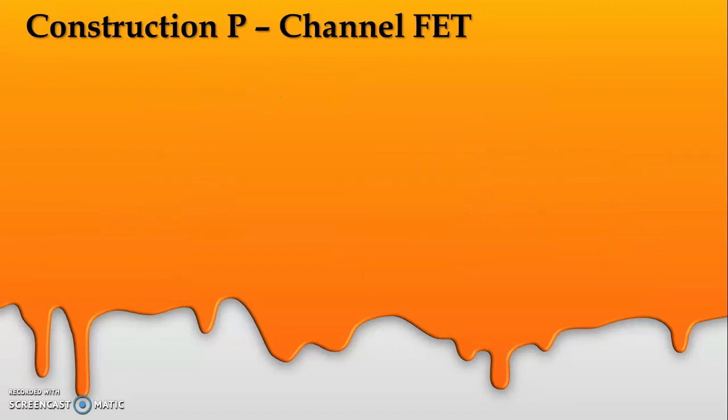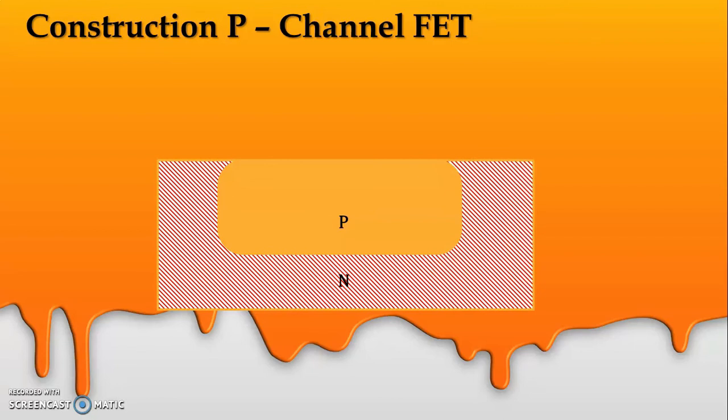Let us see the physical construction of a P-channel field effect transistor. We have P-type semiconductor material as we have discussed, and on both sides of the P-type material, N-type semiconductor material is deposited. The P-type semiconductor material is lightly doped and the N-type semiconductor material is heavily doped.